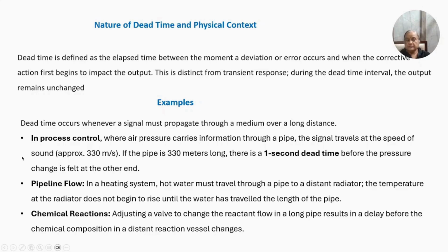So you can imagine how much impact this 1 second dead time will have in this pressure control system whenever some mitigating approach is implemented to bring about some change in the output pressure. This delay will cause a lot of errors and deviation from the set response. So that has to be mathematically properly accounted for while constructing the transfer function itself.